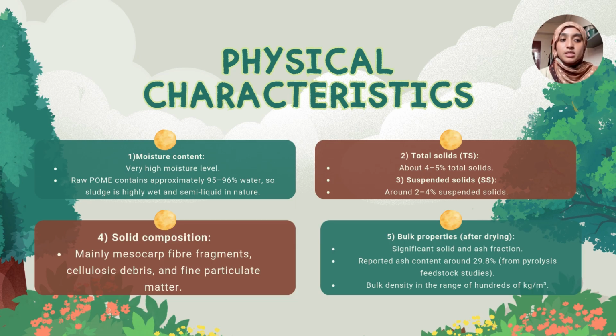And the last one is bulk properties after drying. Its significant solid and ash fraction, with reported ash content around 29.8% from pyrolysis feedstock studies, and the bulk density is in the range of hundreds of kilograms per meter cubed.